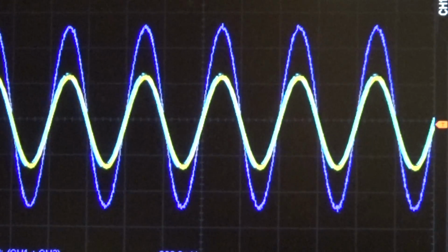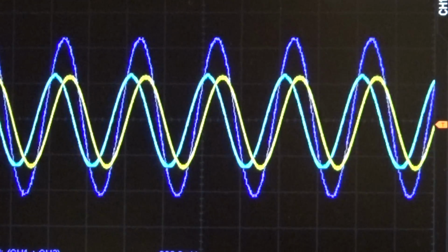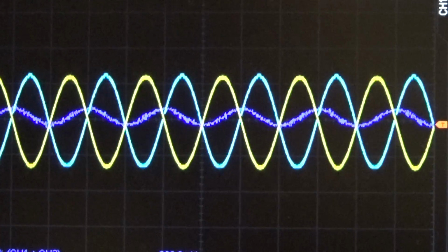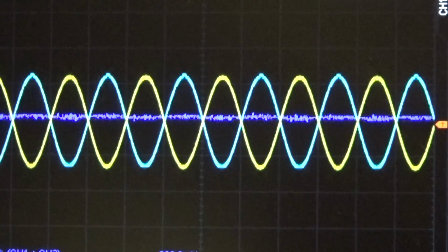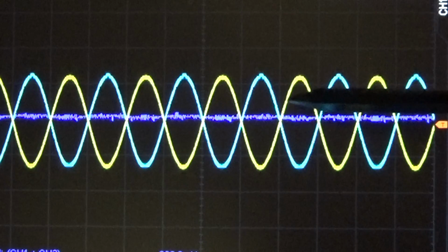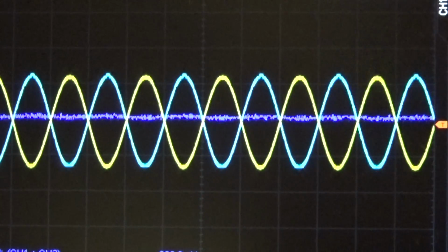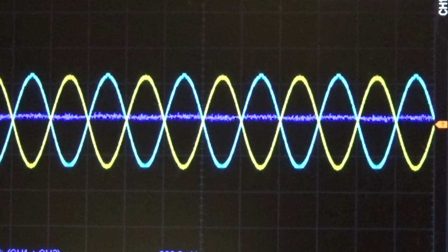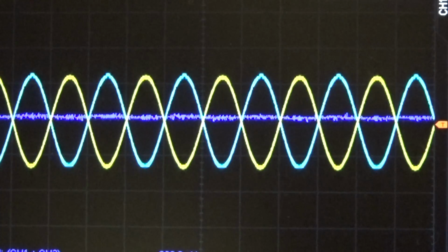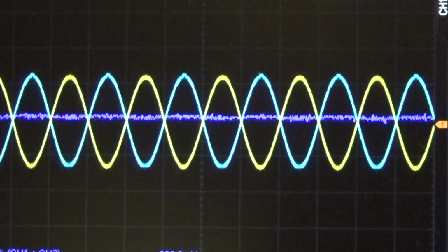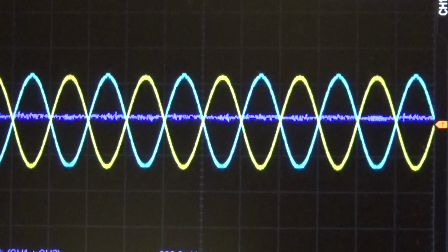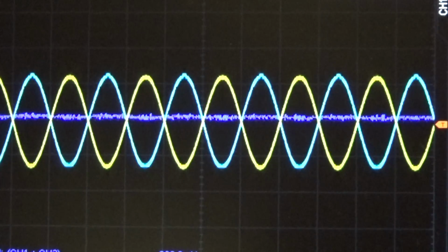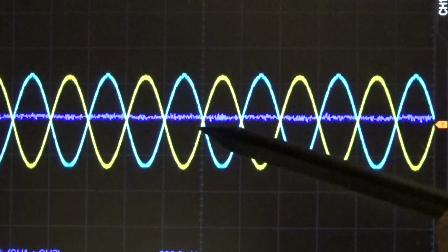And once again, let's shift our phase until we reach 180 degrees, and that is exactly the situation we have in our balanced modulator, and that means that finally our local oscillator component, our HF, or our supporting carrier, whatever you want to call it, is gone.